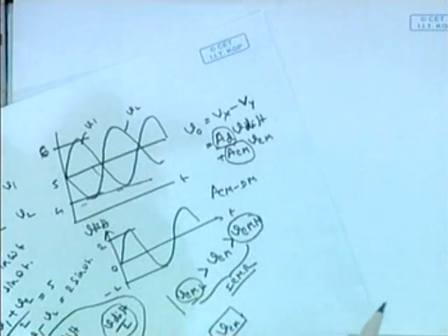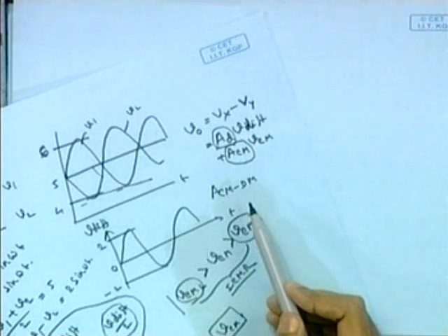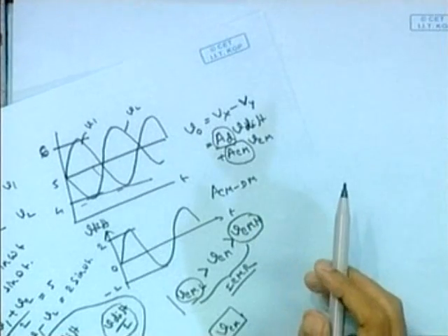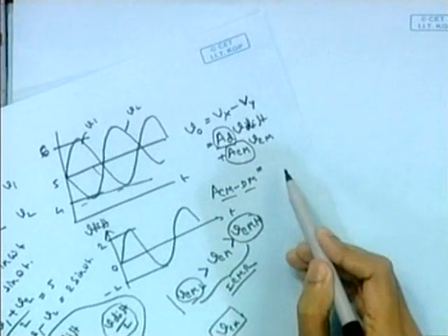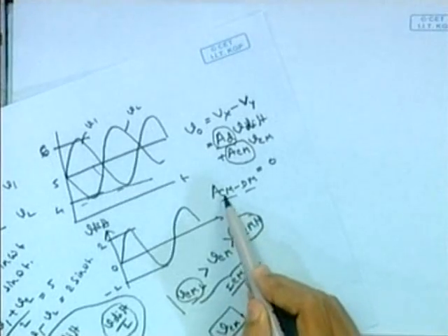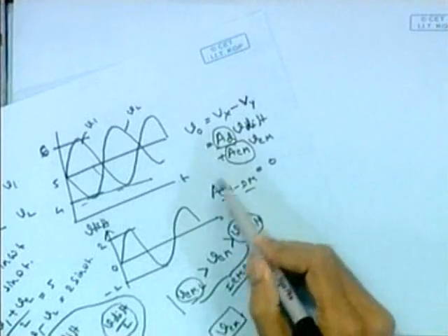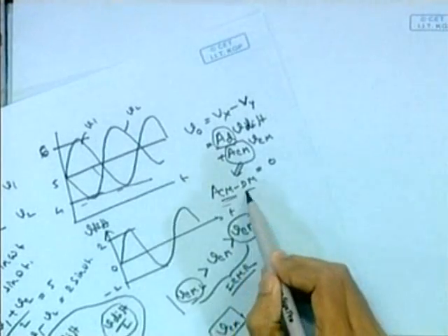But when we are taking the output, we will see that due to some condition or some mismatch or some other thing, we are getting a differential signal, but we should not get that. For an ideal differential amplifier, this CM to DM gain should be 0. I mean no common mode input should appear in our differential output. But in all real cases we have finite values of this, this ACM DM.